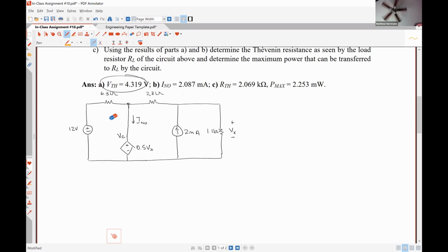And so what I mean by that is if we used KVL, where my mind goes is we would have to use our nodal voltages to determine this current, and our nodal voltages to determine this current, and then add these two currents together and they would give us I Norton, right? Yes, sir. Applying Kirchhoff's current law at that node where all these things are separated.